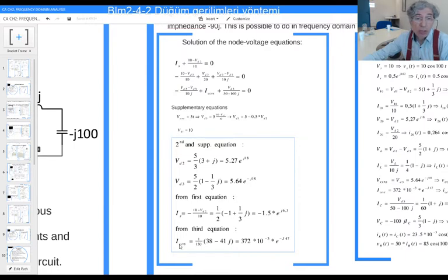And the current controlled voltage source current is going to be calculated from this third equation, because we already calculated VD2, VD3, so we can calculate that VICCVS. So it is this. So what we have done, we have found 5 unknowns.